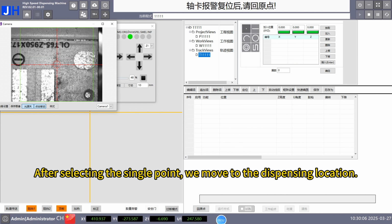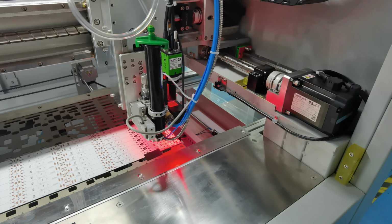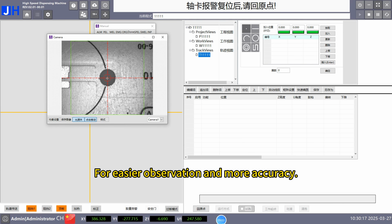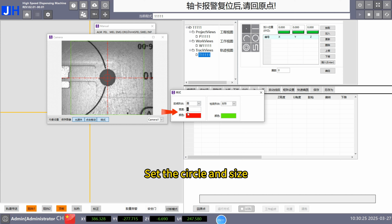After selecting the single point, we move to the dispensing location. Find the location where glue needs to be sprayed. Move to the center of the circle. For easier observation and more accuracy, set the circle size to be the same as the actual circle size. Set the circle and size.